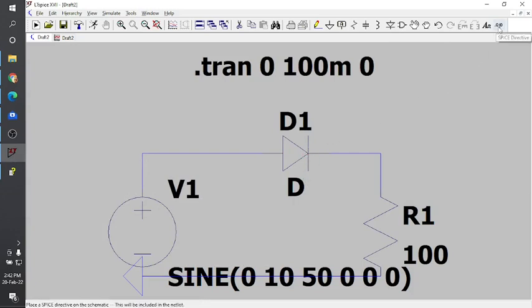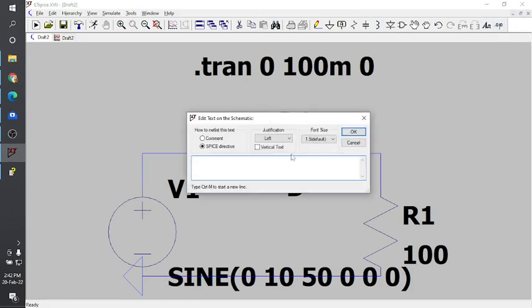So what I can do here, in the third toolbar, if you follow my cursor, then here the SPICE directive is open, and you have to write a dot. Maybe it will not appear in your screen because of the small screen, so I will show you. So dot model, capital D in brackets, it is a command.